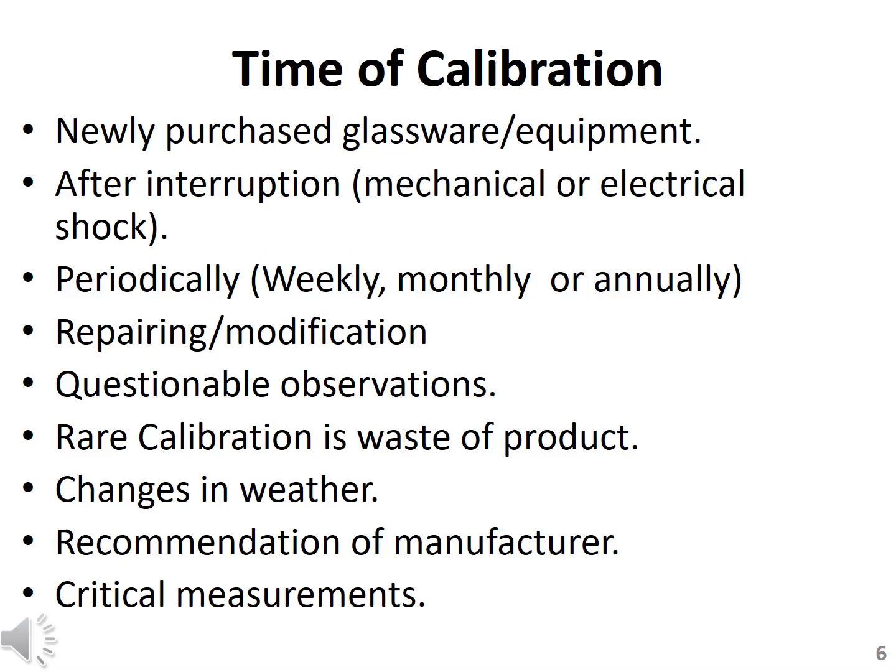Okay, when will the calibration be done? This is a very important question. Here I list some cases in which we are going to calibrate the instrument or equipment. Number one, when you purchase new glassware, new equipment or instrument, definitely you need to calibrate that newly purchased glassware, equipment or instrument. If you are using that glassware or equipment without calibration, there are chances that you will get results that are not accurate or not precise.